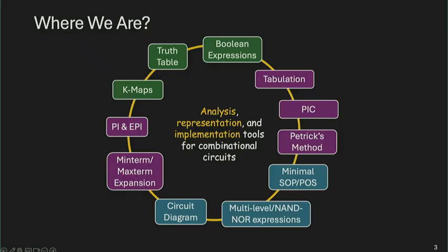And essentially every circle that you put in the K-map for those prime implicants will translate into one row in the prime implicant chart. And essentially you're solving the very same coverage problem, right? Just in K-map you have like a two-dimensional coverage relationship. In a prime implicant chart, all the implicants go to one side. So yeah, think about the correlation of these topics a bit more.